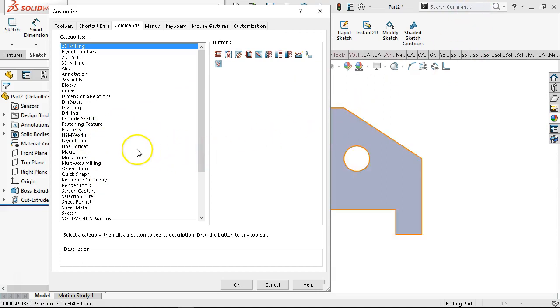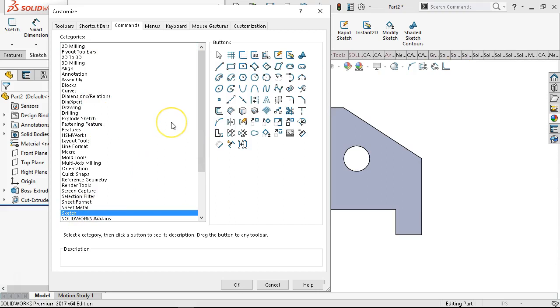you're looking for. But in the case of the heads-up display, maybe I want to add something from the sketch that I use often. So split entities is one of those items that I use pretty regularly. As opposed to trimming, I will split entities and leave them in place, turn them into construction lines, and it is an effective strategy. To a certain extent, I don't know that I've trimmed anything in a couple of years now.